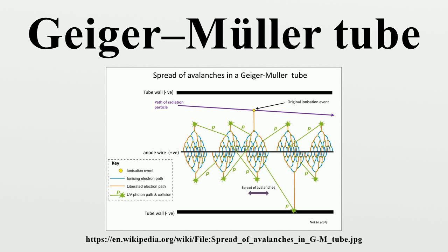This correction is achieved by energy compensation of the tube, which modifies the number of count events in accordance with the energy of the incident radiation by using an external filter collar of energy absorbing material. The collar has an increased attenuation of low-energy gamma, and so compensates for the increased energy response of the naked tube at those levels. The aim is that the sensitivity, energy characteristic of the tube should be matched by the absorption, energy characteristic of the filter. This results in a more uniform response over the stated range of detection energies for the tube.